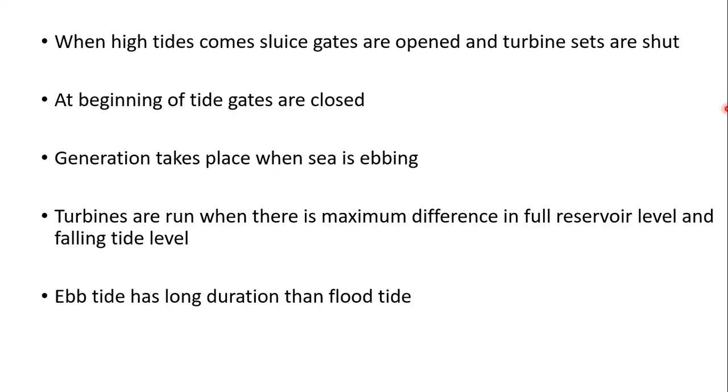All these turbines may be reversible, which can work as pumps after the high tides in order to increase the amount of water in the storage lake until the generation starts. This way turbine operation may be prolonged to 10 or more hours. So we are having 12 hours, and out of 12 hours, we are running the turbines for more than 10 hours.